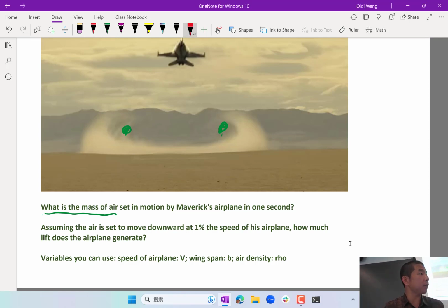What is the flow field induced by the vortices? You may not remember the formulas, but I hope you still qualitatively understand what the flow field around a vortex looks like. You can just add up the two vortex flow fields to have a velocity field like that. Away from the vortices, the flow velocity is going to be smaller, and near the vortices, the flow field is going to be stronger.